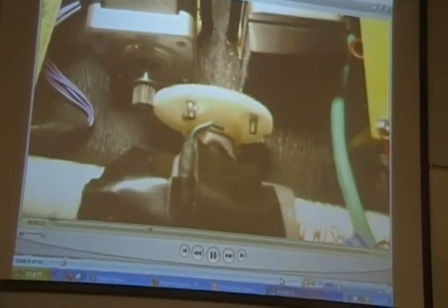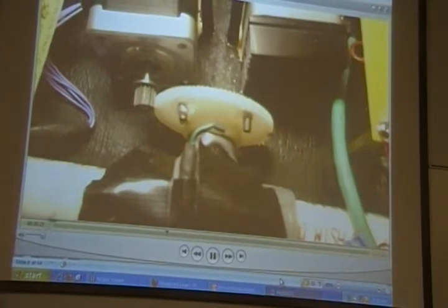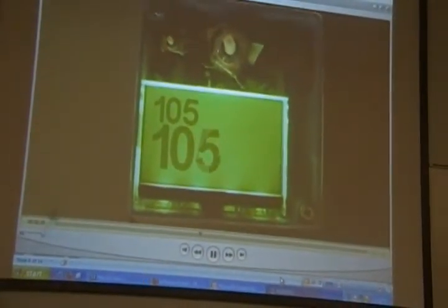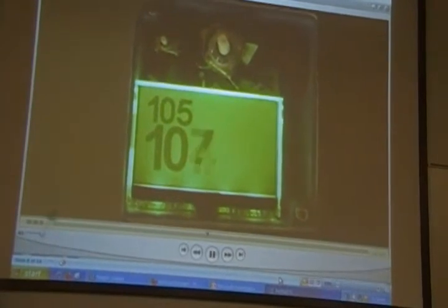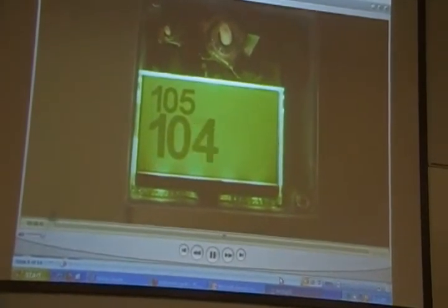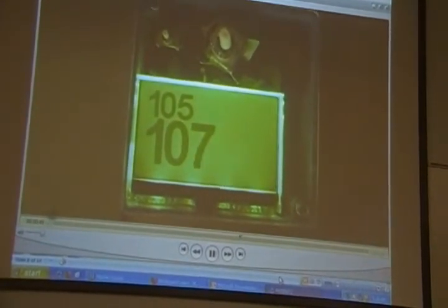This valve is the cold valve. The stepper motors are receiving commands from the main microcontroller over the I2C connection and turning as necessary. So now you can see that the output temperature, which is the large number, is within the 2 degrees plus or minus tolerance of the desired temperature. And you'll notice that the output temperature is actually fluctuating a bit, and we'll talk about that in a minute.